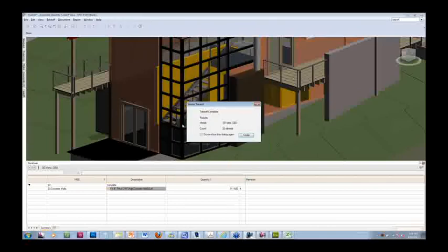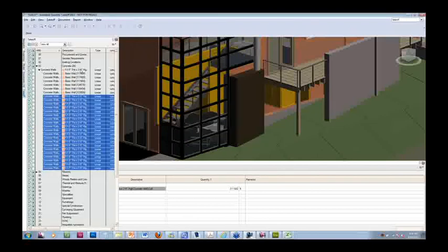So when I select them, watch this, automatically they're mapped. And when I go now to my takeoff tab, you'll see them all listed here. And if now all I do is create a report for saying, what is now the total cost, I can just keep exporting. So really the power of QTO lies in the catalog. If you build it, you can have it as automated as possible, because then next time you get a new model, and typically some people do this at different milestones in the project, because it's pretty static. It doesn't have a link.